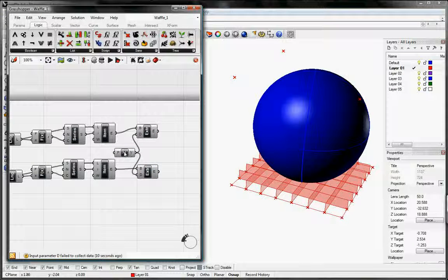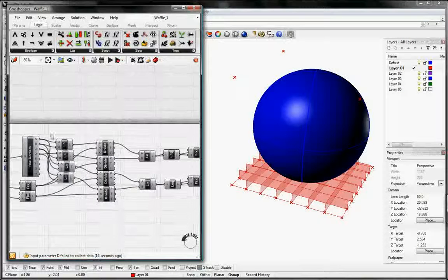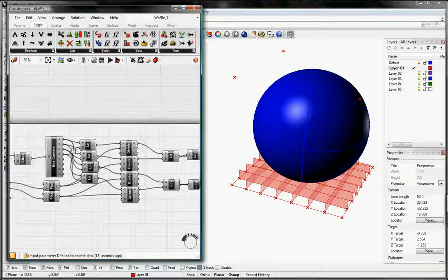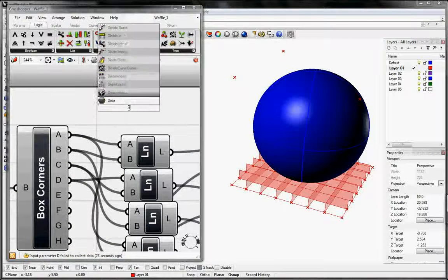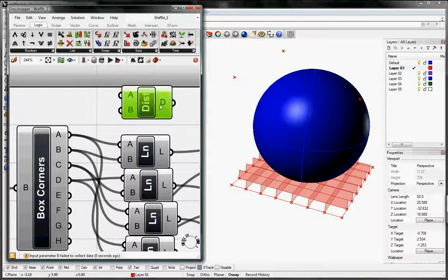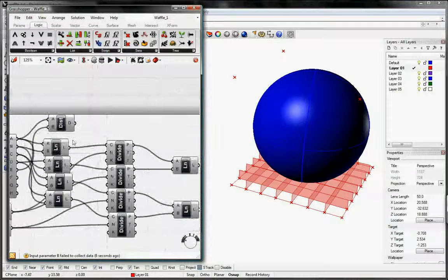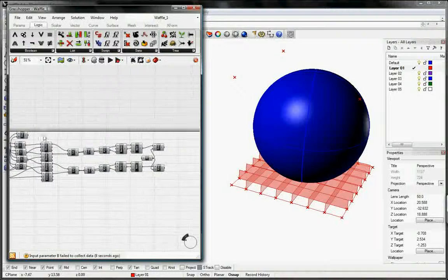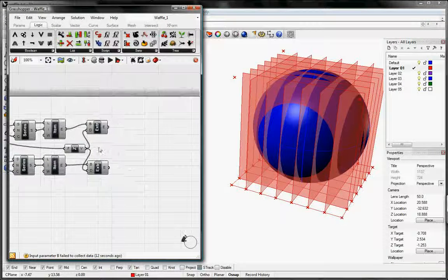The unit Z starts out with a 1 unit, so the unit we actually want to be related to our box corners in the beginning. So I'll zoom into the box corners and then grab a distance button, and here we'll just measure the vertical distance. So we'll start at the A point and then measure to the E point, which is the corresponding box corner above it, and then that D distance we'll take and throw into the Z unit, and you'll see they pop up right there.